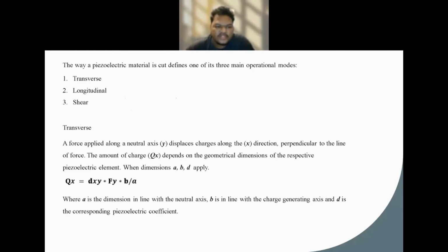Transverse is a force applied along a neutral axis y, displaced just along the x direction, perpendicular to the line of force. The amount of charge Qx depends on the geometrical dimensions of the respective piezoelectric element. When dimensions a, b, and d apply, this is the equation for transverse, where a is the dimension in line with the neutral axis, b is in line with the charge generating axis, and d is the corresponding piezoelectric coefficient.